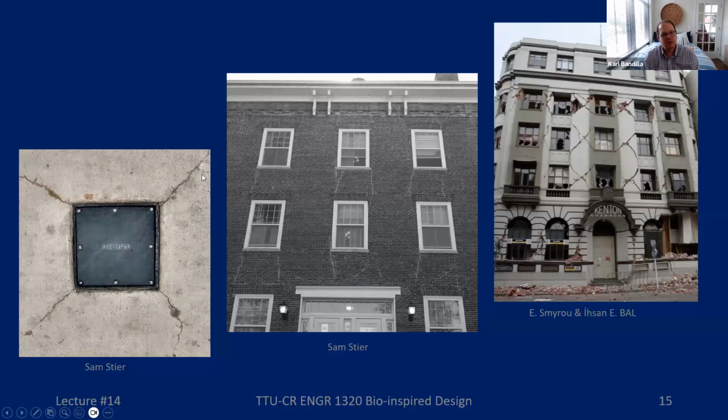So this sidewalk is cracked along where the corners are. That's just because of the stresses in the concrete. For the concrete, this is kind of a cut right here, so the stresses are going to be the highest there. You can walk around, maybe not near your neighborhood because the houses are too far set back and the walls around them are too high. But if you walk through an urban neighborhood, you'll often see cracks forming right at the corners of windows.